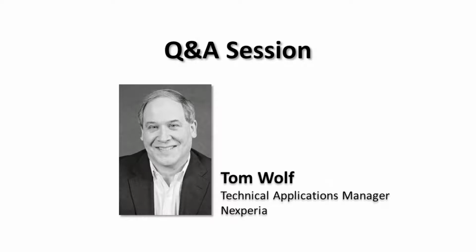Okay. Thanks, Bill, for that question. We actually touched on that during the presentation. Some of the part numbers start with PSMN, some of them start with BUK. Silicon is the same. They're still essentially the same parts, same voltages, same RDS on. A BUK part is automotive qualified, Q101 qualified, so we give it a BUK number to identify that. PSMN is a commercial grade part, but other than that, they're both MOSFETs. The same rules apply to them, the same simulations apply. The book is accurate for both of them. It's just commercial versus automotive grade.